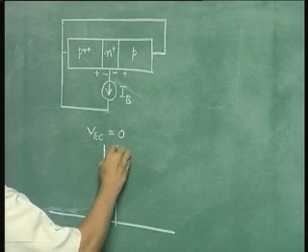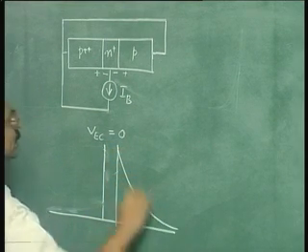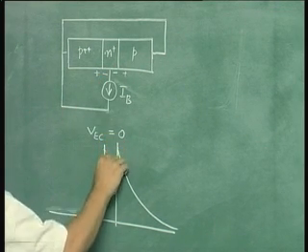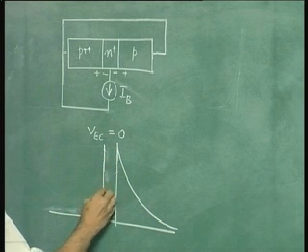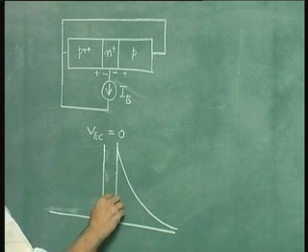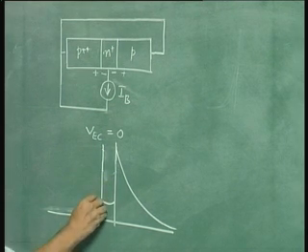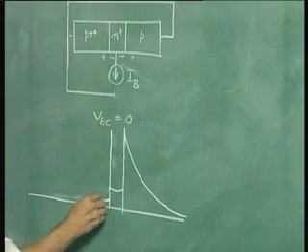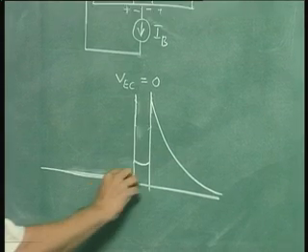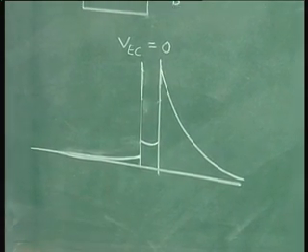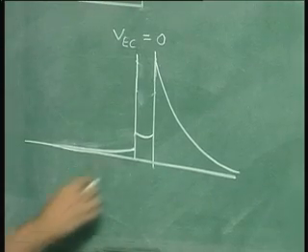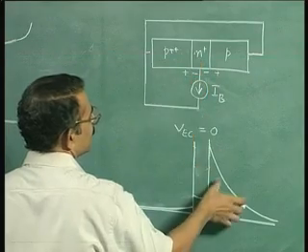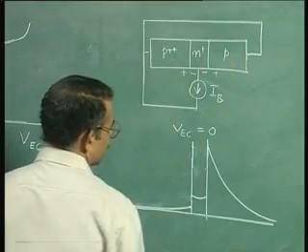So we first draw this excess carrier concentration because this is also forward bias now under this condition. Please note that this is a forward bias across the collector base junction. Now this is 1/10 of this inside here. So still I cannot show 1/10, but at least roughly very small, and this here is something like this, because this is again 1/10 of that. So this is how the excess carrier distribution would be. This is excess electrons in the P region, this is excess holes in the N region, this is excess electrons again in the P type collector region.